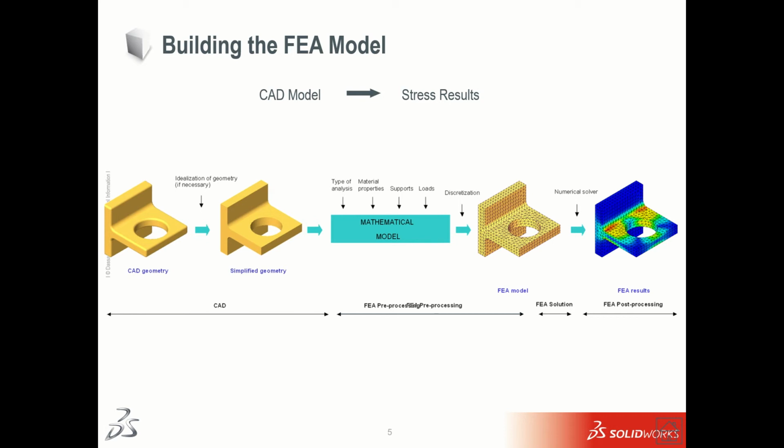There are basically five material properties you need to know for a static analysis. One is the yield strength, Young's modulus, density, Poisson's ratio, and ultimate tensile stress. These five parameters you need to know.